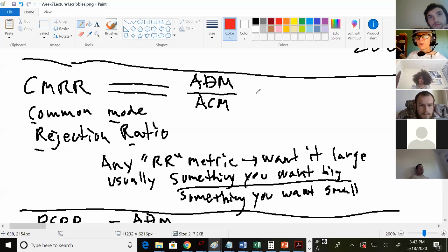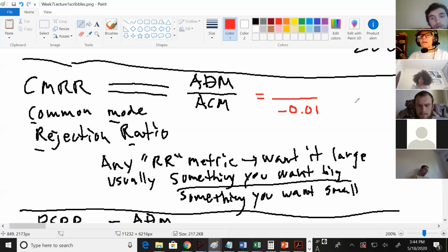it is pretty small. Let's say made up numbers. We know this is negative 0.01 from our last example. And if we have an RC of 2K and a GM of, if our VT is 25.9 millivolts, and you divide that by 1 milliamp, then you get 25.9 times 2K.